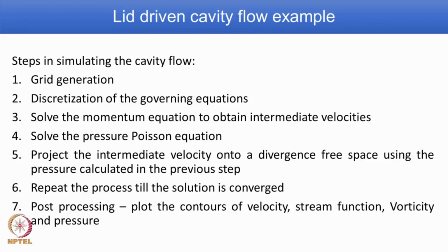Once you get the solution, then we are interested in post processing. Post processing of the results can be in many forms. You can have contours, you can have lines, or you can go for advanced post processing: stream function, vorticity contour, and so on.